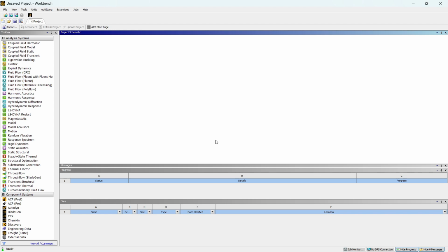In our case, we'll simulate a tube bank, where water flows through and around a series of pipes. One stream of water flows inside the tubes at one temperature, while another flows across them at a different temperature. Because the setup is symmetrical and periodic, we only need to model a small part of the geometry. We'll define periodic boundary conditions in ANSYS to represent this repeating nature, saving time and computational effort while still getting accurate results for flow and heat transfer.